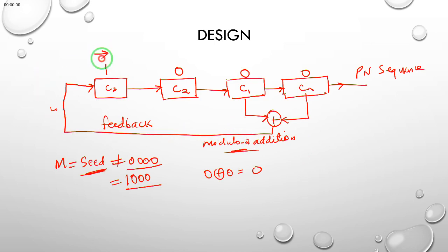But they are called shift registers. So in our next cycle, 1 comes here, this 0 comes there, and the next one comes here as 0, and the next one comes here as that. Now our new digit that we have obtained is this 0 that we have received from here. And then we evaluate 0 XOR 0. I will look at the scenario in the next few slides.